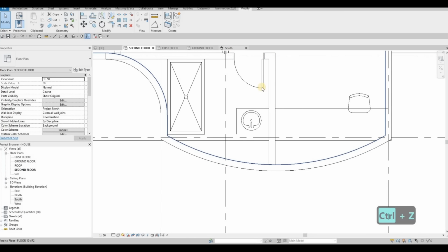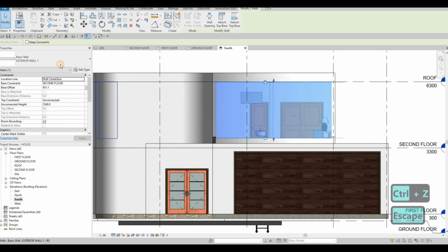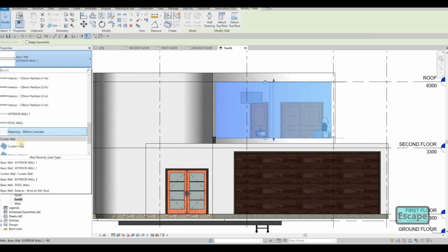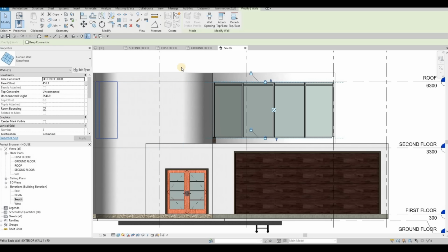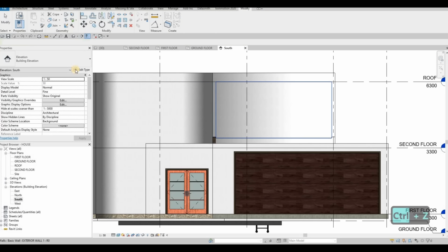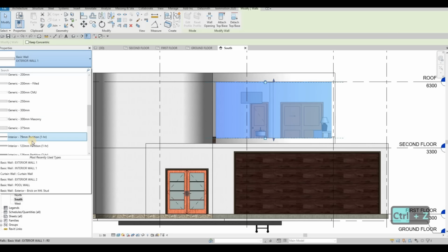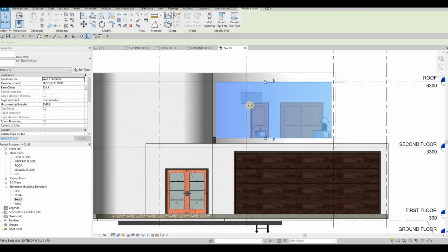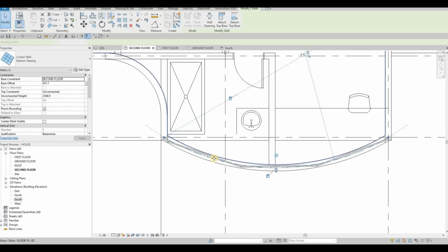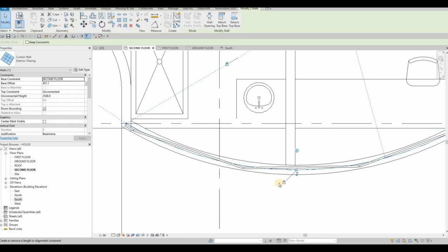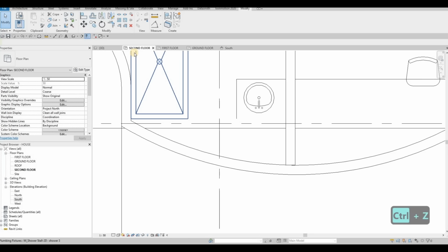So the technique now is to select this and do a storefront. Even the other one, exterior glazing, we can do it, but as you can see, it's like this. It's not actually curved. It's per panel and the mullion is not there.